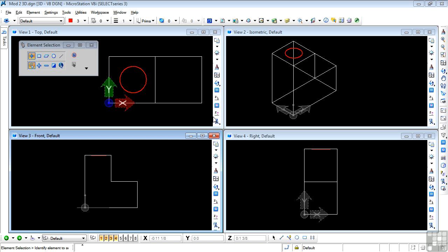Setting the location of clipping planes is similar to setting the active depth, in that you need two perpendicular views. Let's set the display depth in the top view, and you'll see how this works. Now at the moment, the active depth is at the top surface of the step block. We drew the circle using the fact that our active depth was in the top surface.